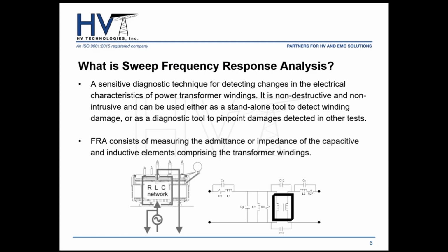So now you know about the instrument and what you'll get, but what exactly is sweep frequency response analysis? When we're talking about FRA analysis or sweep frequency analysis, we're talking about a diagnostic technique that is used for detecting changes in the electrical characteristics of a power transformer winding.